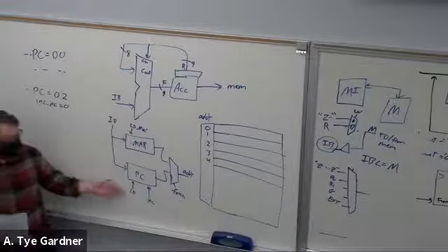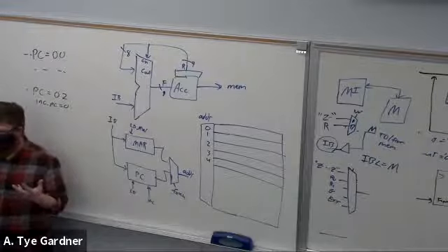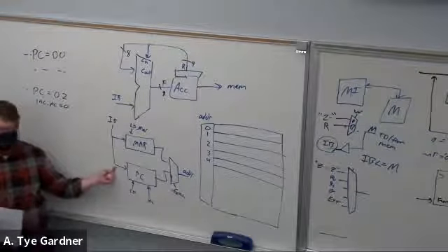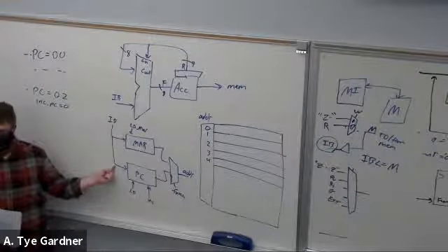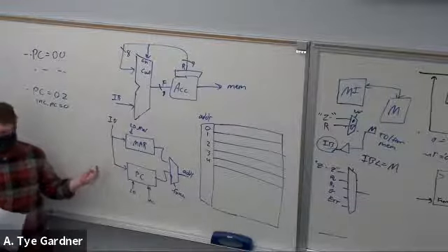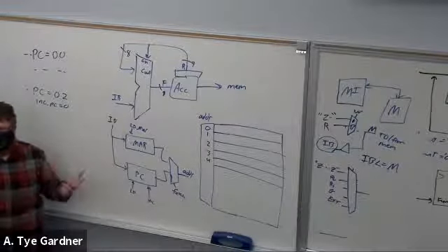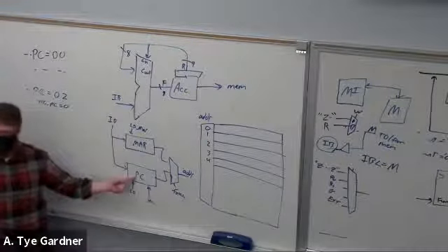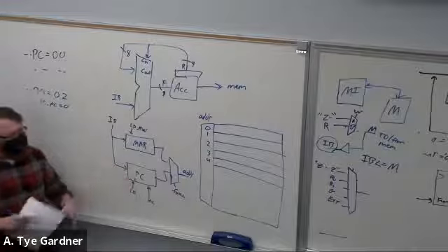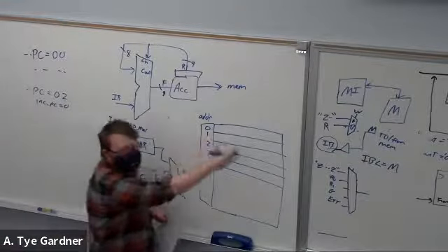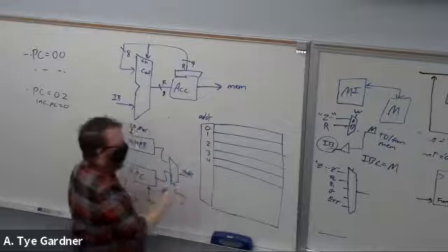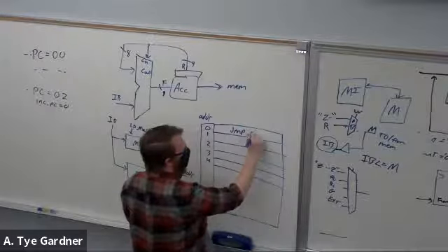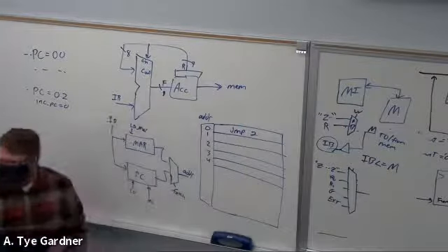Okay, so the loads are just parallel loads. What they do is if they're asserted, they bring in whatever value is on IB. Why would you do that? Well, let's say the system wanted to start at somewhere that wasn't 0. Well, my counter starts at 0. Well, the first command, I have to do something at 0. There's no other way because I don't have a way of asserting load command. So I could do like jump to 2 or something like that, right?